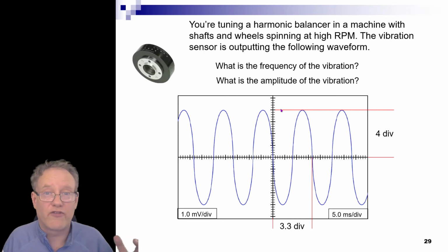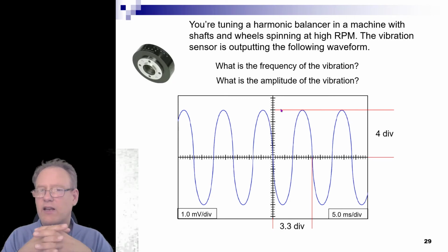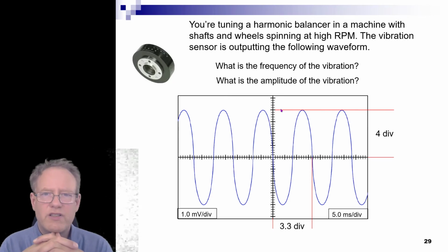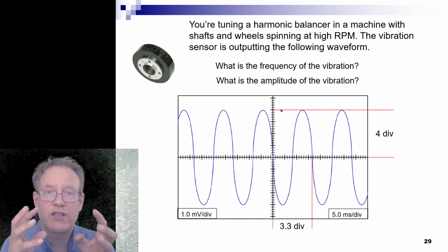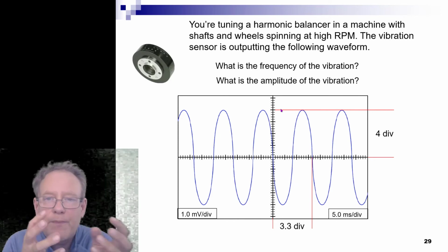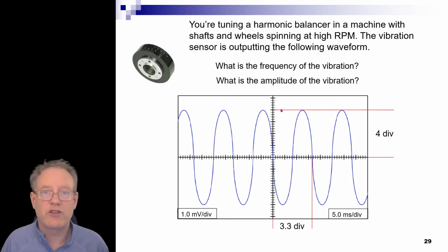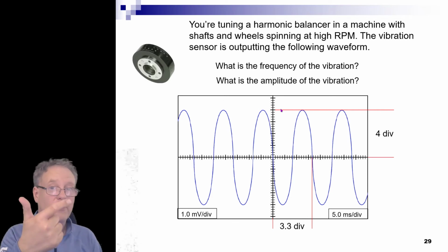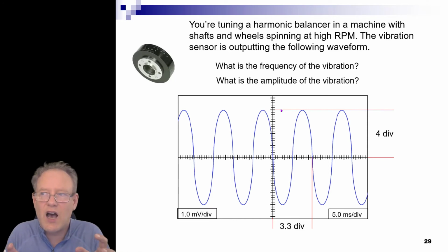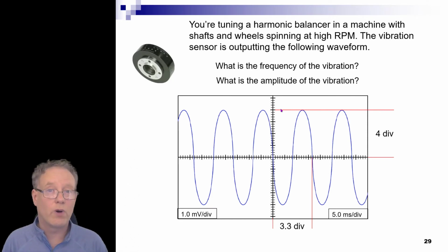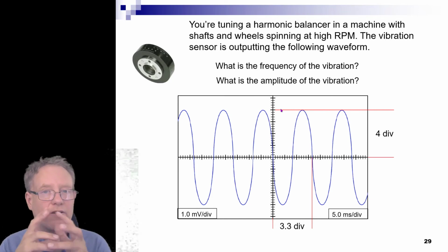Well, I can go get a frequency sensor or a vibration sensor, and then see, I said that wrong. I said it's a frequency sensor. There's no such thing as a frequency sensor. It does not exist. There's a sensor that senses vibrations, senses oscillations of some physical something that's changing, or something we can measure that's changing or alternating, and we can tell you the period of it or the frequency of it. So it's not a frequency meter per se. You're studying the frequency of electrical oscillation if you want to take a look at it, but it's a vibration sensor, not a frequency sensor.